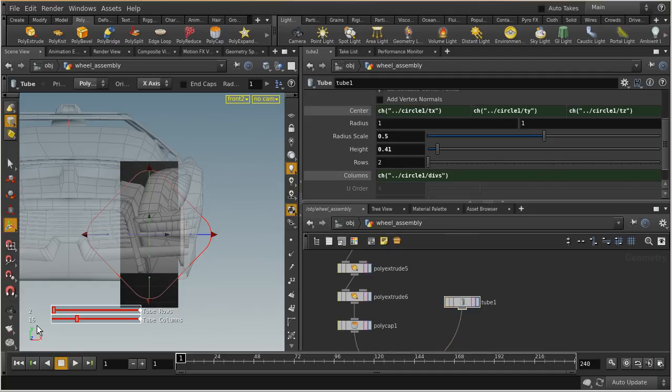Now I can look here and see by this little indicator in the bottom left-hand corner of my viewport that it is X, that I want to push this to the right in X. Well, X is locked down now to this, but I can always add to it. Very simply, all I did was click inside that particular channel, and I'm going to type in space plus space, and let's just try 0.05 for right now, something to try.